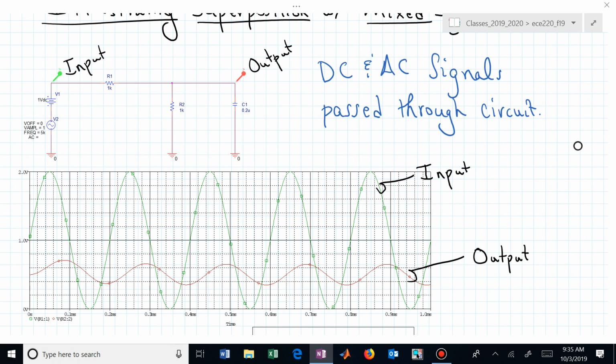And that's actually, if you can see it, the green waveform. We had an amplitude of 1 on that AC waveform, which means that it should be -1 to +1. But wait a minute, it's going from 0 to 2. Well, that DC source has shifted it or offset it by 1 volt. It's now moved that -1 to +1 AC waveform up, and now this sinusoid is all positive. It's going from 0 to 2. That's our input. We're applying that to this new circuit for us.